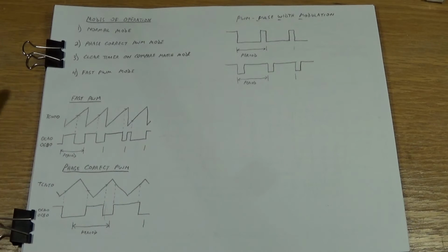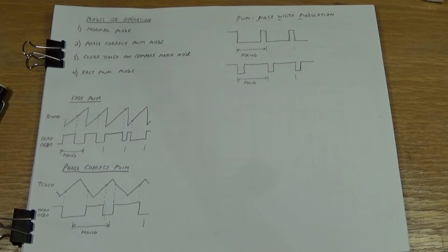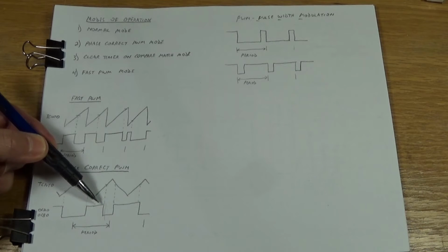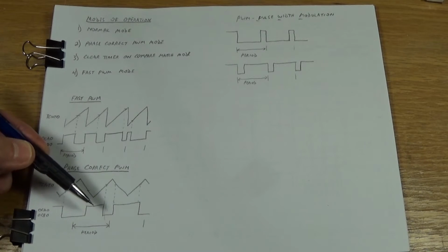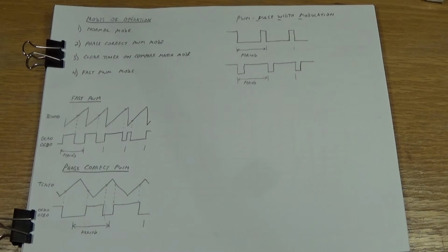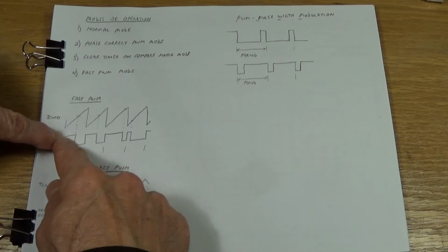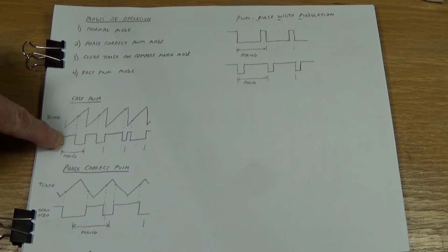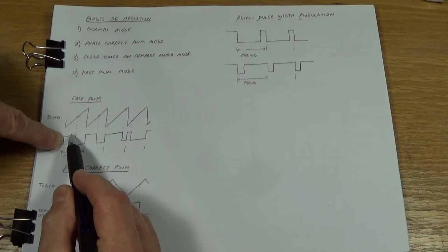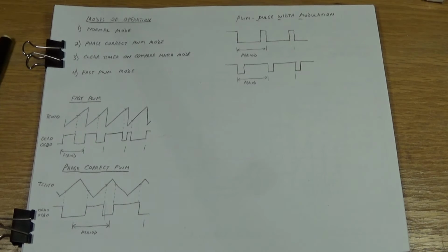And so when you vary the PWM in this mode, what you're going to get is these pulses here getting wider or narrower. Again, the period is the same, so your on time per period is going to be determining the duty cycle of the PWM. In the fast PWM mode here, what you're going to see is always a rising edge here, and then the falling edge here just moving back and forth as you change the value in the output compare register.